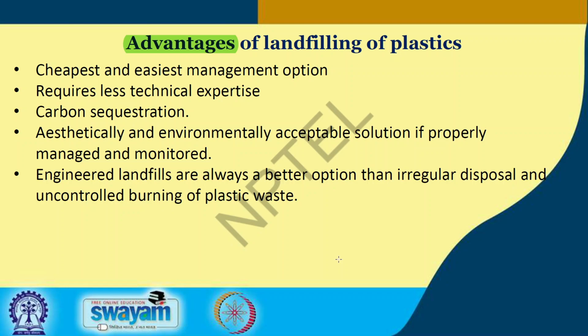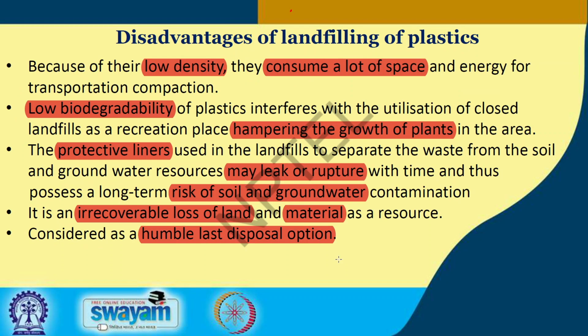But we have some advantages for landfill, like it is the cheapest, easiest option, because transporting the waste to a nearby site and just dumping it in the open land is the cheapest and easiest option. And it requires no technical knowledge, just less expertise. Carbon sequestration, and an aesthetic and environmentally acceptable solution if properly managed. Not open dumping. An engineered landfill will be aesthetically and environmentally acceptable. And engineered landfills are always a better option than irregular disposal and uncontrolled dumping of plastic waste.